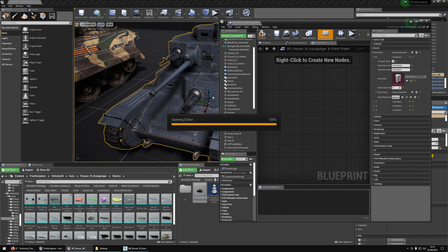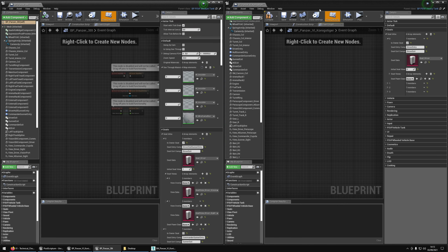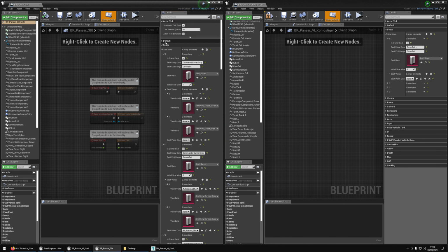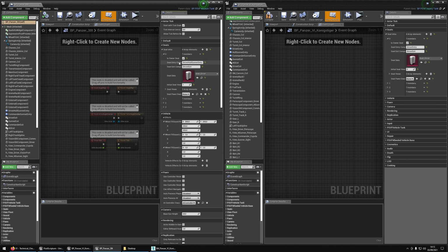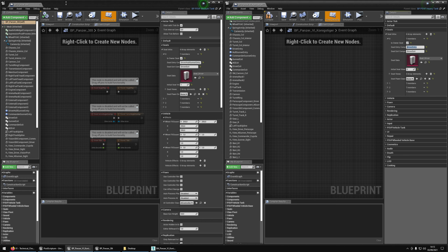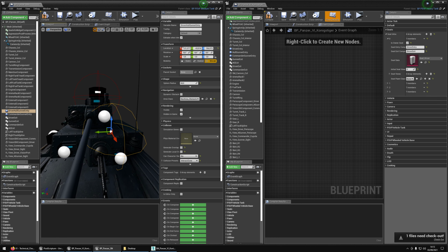That looks pretty much like this. I'm going to have the 3080 on the left and the King Tiger on the right. Let's look at the seats. For the driver, we can see the seat entry component is driver, hull gunner entry, while on the King Tiger it's just driver entry. What that is doing is looking at this volume, and the name of this volume is driver, hull gunner entry. The name of that sphere is actually more than display; it is what the system is looking for.